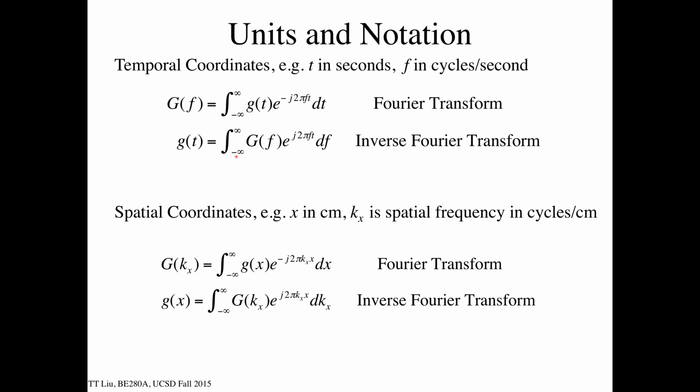And given the spectrum, I can take the inverse Fourier transform of the spectrum and reconstruct the actual waveform itself, the original sound waveform. So I have an equivalent amount of information in the spectrum as I do in the original time domain signal. And this can be used to your advantage a lot, right? If you want to compress something and you have, say, I don't know, 100 seconds of sound, and you're trying to figure out what are the really important features of this sound wave?